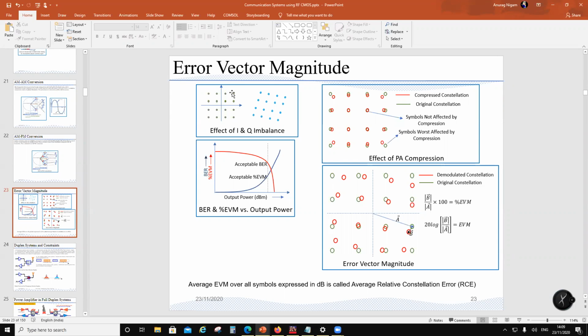I would rather look at the signal statistics, and accordingly I will allot the bins so that my peak to average ratio, which I will talk about later, is minimized. So I have a smaller constraint on linearity. We'll come to that. You just accept that these are not allocated as is, but per a certain algorithm to minimize PAPR, or peak to average power ratio.